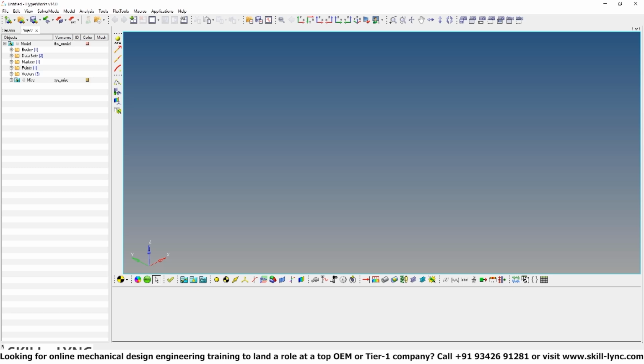Welcome back to the demo on exercise 7. In this exercise, you'll reuse the simple pendulum model created in the previous chapter to add 2 more bodies and 3 more joints to create a 4-bar mechanism. In the process of creating this, you'll also investigate the redundant constraints and modify your model to remove them.